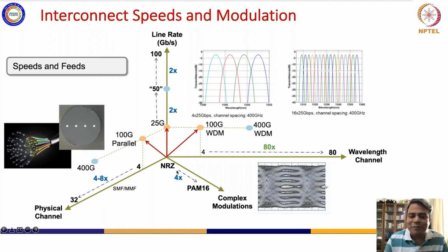What you can do, we talked about simply encoding, right? So you can encode more, rather than having a voltage level represent a 0 and a 1. You can actually do encoding so that you can carry 2 bits in every clock cycle. You can increase the clock cycle itself. Rather than clocking data at 25 gigabits per second, you can do it at 50 gigabits or 100 gigabits.